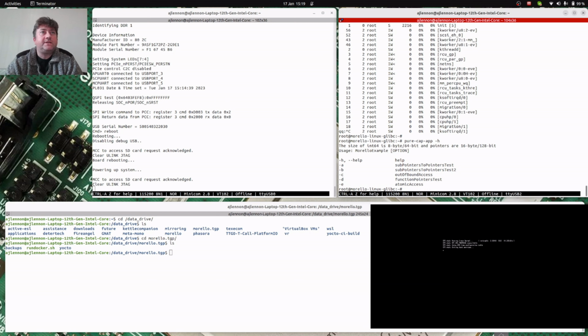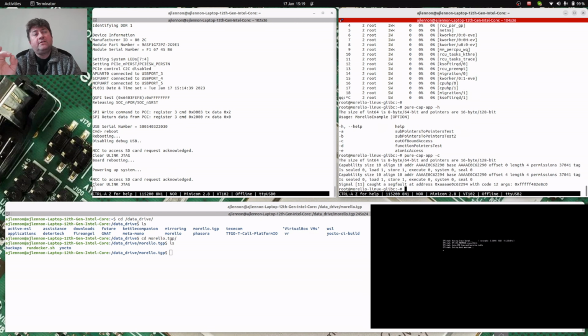It's got a couple of initial basic tests we can run, and we can run, for example, an out of bounds memory access, which runs, and then there is a signal being caught when that errors by CHERI, coming back to a signal handler for us and telling us, no, you're not allowed to do that. So that's a really basic example of how we can begin to build Yocto support to protect us using this CHERI architecture. And what I'm now going to do is to move on and show you how we build this up and how we get this onto boot on the Morello platform.